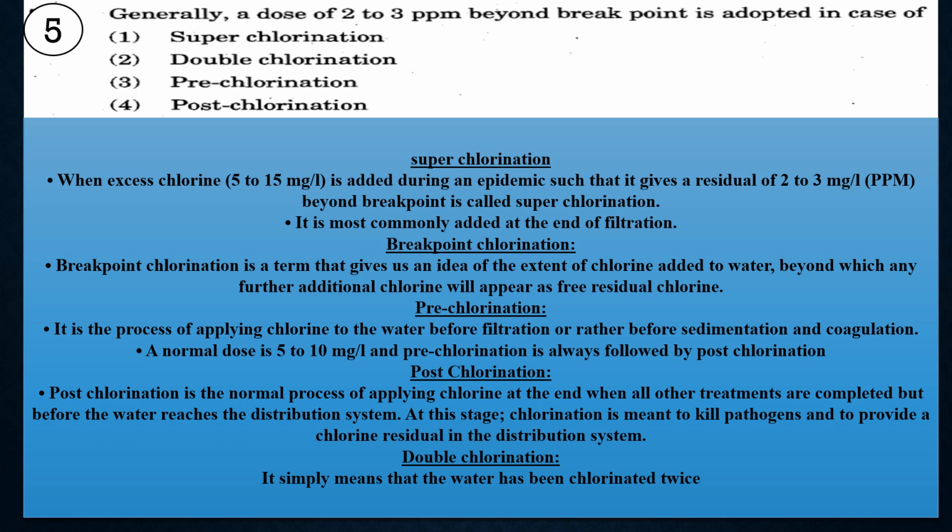Then in the case of post-chlorination, it is the normal process of applying chlorine at the end, when all the other treatments are completed. Double chlorination simply means that the water has been chlorinated twice. So for question number 5, the first option is correct, that is superchlorination.